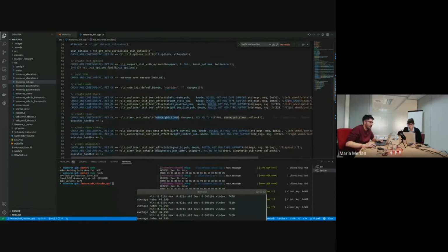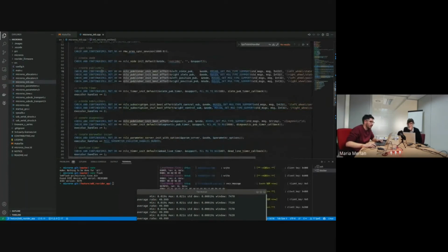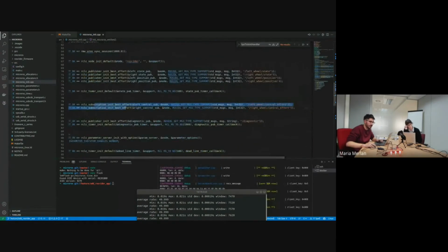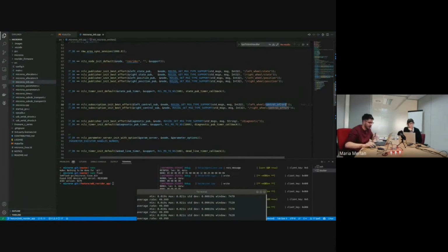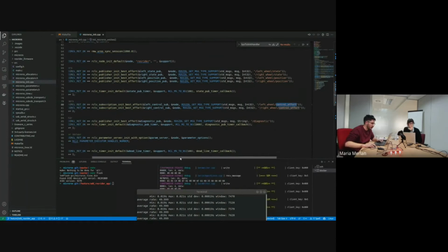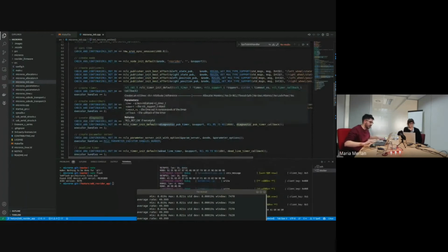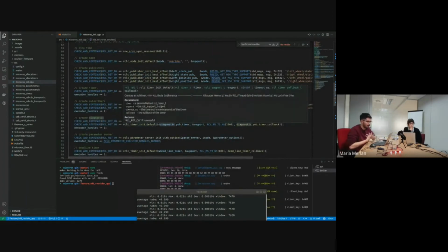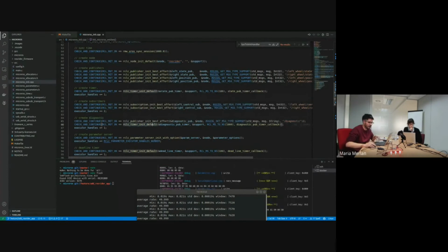We are also creating a timer for publishing this information. We have also a couple of subscriptions in order to receive the control effort that we need to apply to a certain motor, maybe the PWM duty or anything that can be related with how much voltage we should apply to a motor. We also have here a diagnostic publisher that we will see at the end. Here I am printing just information about the stack, heap, and some voltages, in a really basic approach.